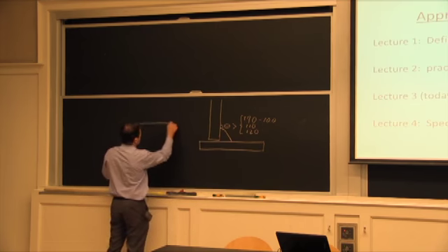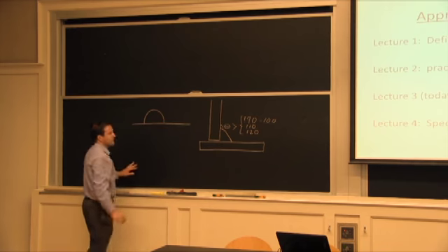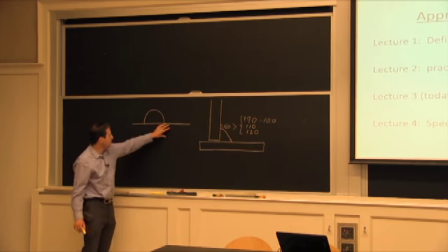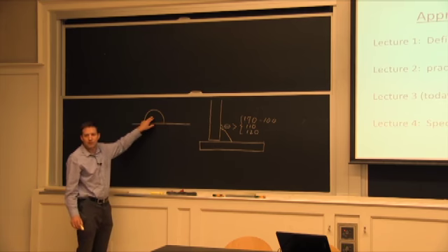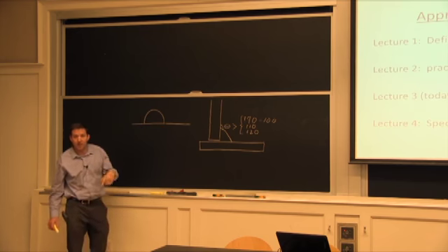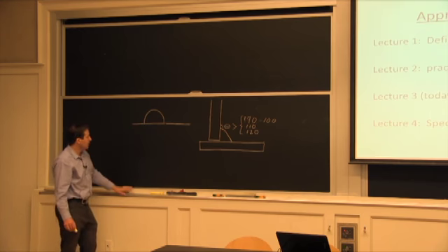Let's say we have a flat surface and we have a bead of metal on it. If the bead is looking like this, that's a cold weld. This is a situation of a cold piece of metal in which you put the liquid metal, and there's a high surface tension between them, and that's why it's bulging up, a little bit like paraffin would do this behavior.